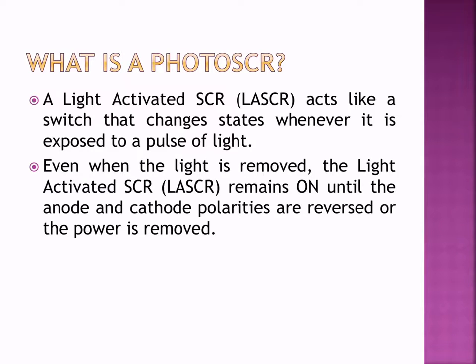What is a PhotoSCR? A light-activated SCR acts like a switch that changes states whenever it is exposed to a pulse of light. Even if the light is removed, the light-activated SCR remains on until the anode and cathode polarities are reversed or the power is removed.